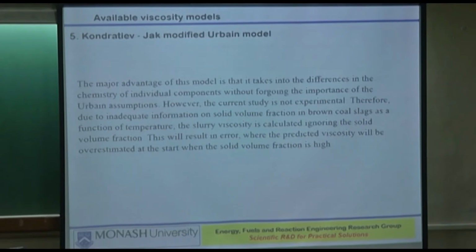And the other thing is, if we want to apply this model for any prediction, then we need to know in our slag what proportion will be crystalline compounds and what proportion will be non-crystalline compounds, because that will stay between 0 and 1. Of course, if everything is crystalline solid, then the question of viscosity doesn't arise. But if it is closer to 0, then it will be close to a full liquid, even though it will be non-Newtonian.